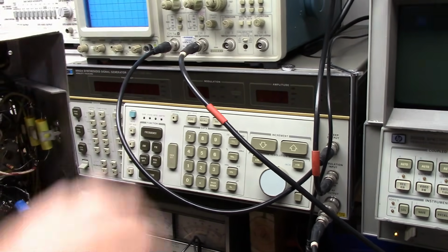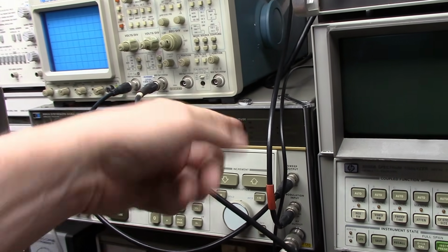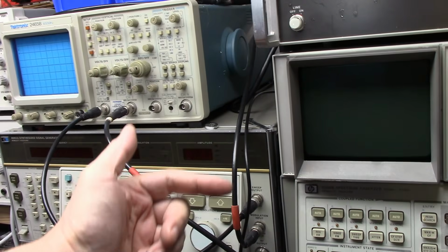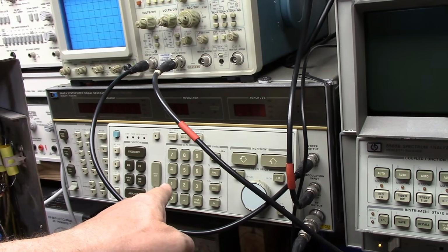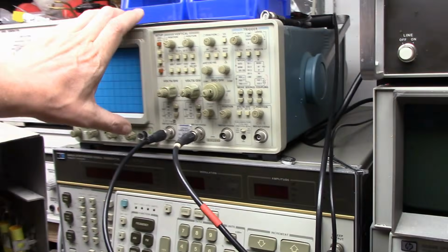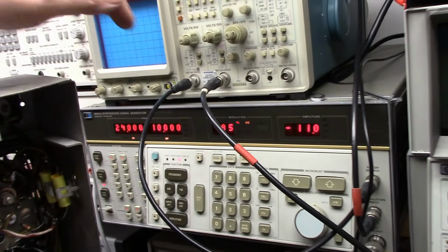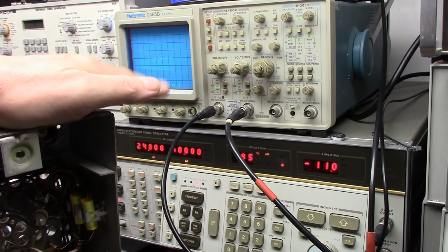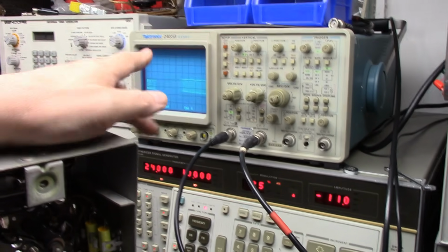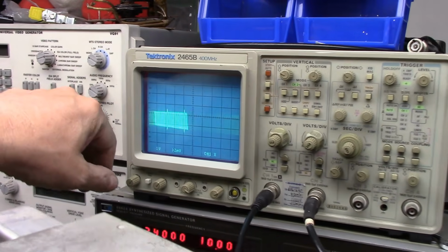Okay, so what can we do with that? Well, the service manual for this says what you can do is take the output from the back of this with that triangle marker and feed it into the modulation input and enable AM modulation on this, and make more traditional birdie markers, which are like little weird fluttery things where the markers are. So I've got this rigged up so we can see that. Sort of. It'll work a lot better when we actually have a device under test, but this is enough that we should be able to see them. And sure enough, there they are.